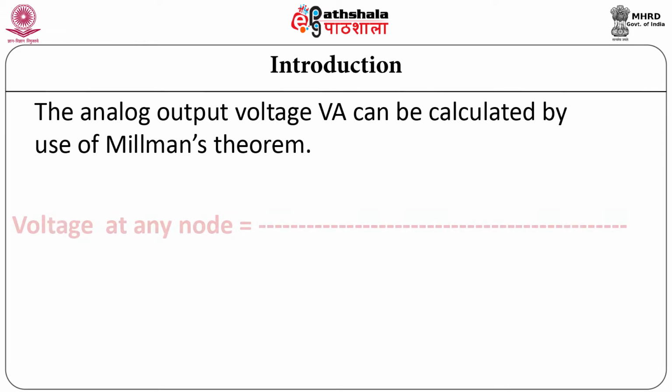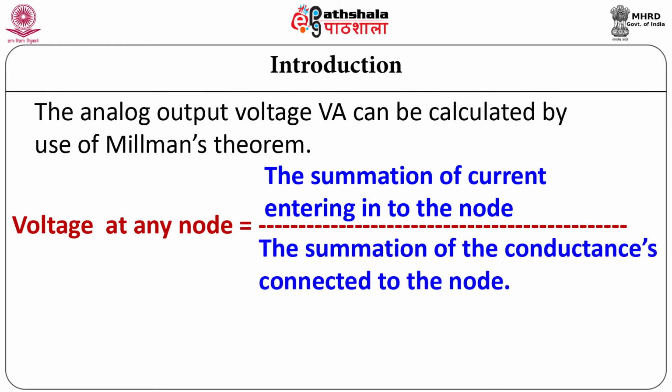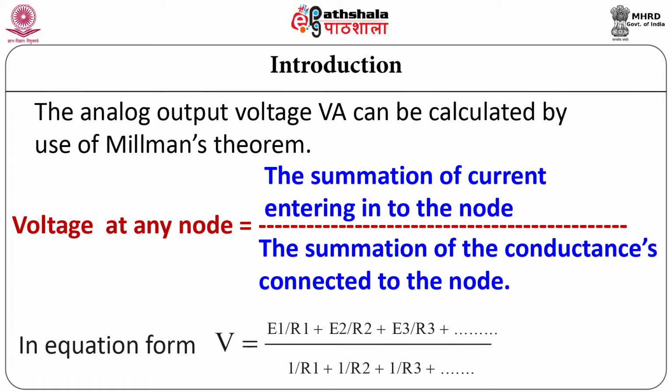According to Millman's theorem, voltage at any node is the ratio of summation of current entering the node to the summation of conductances connected to the node, and hence in equation form equivalent analog voltage VA can be written as VA equals E1/R1 + E2/R2 + E3/R3 + ... divided by 1/R1 + 1/R2 + 1/R3 + ...